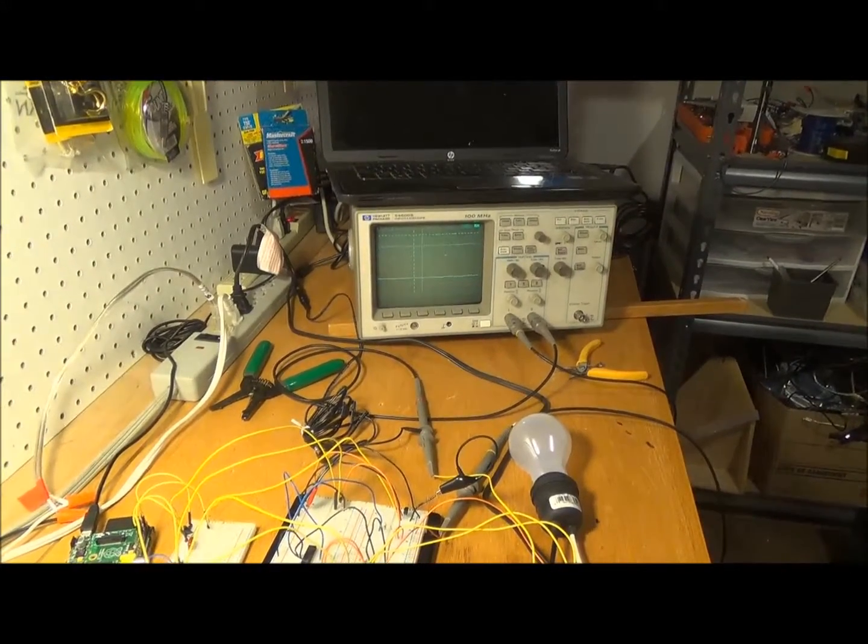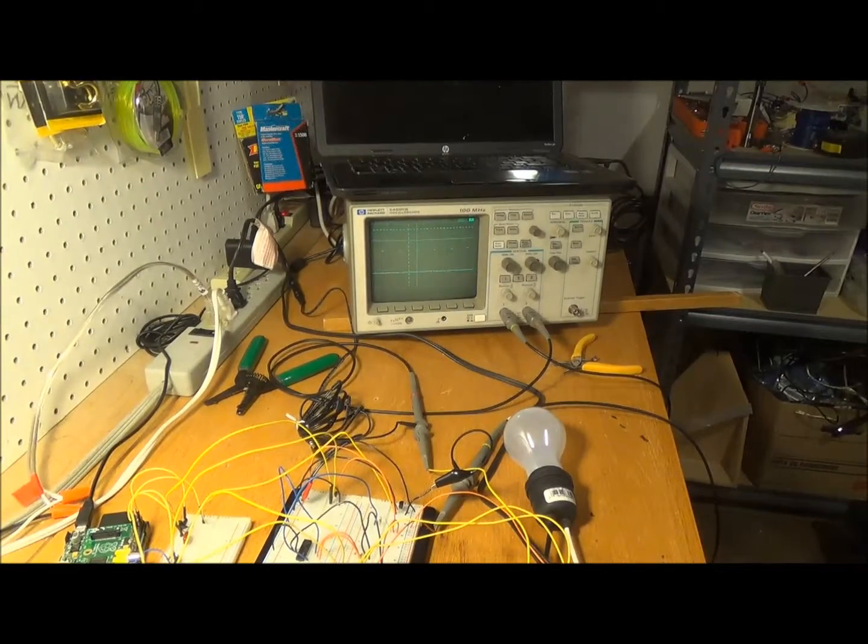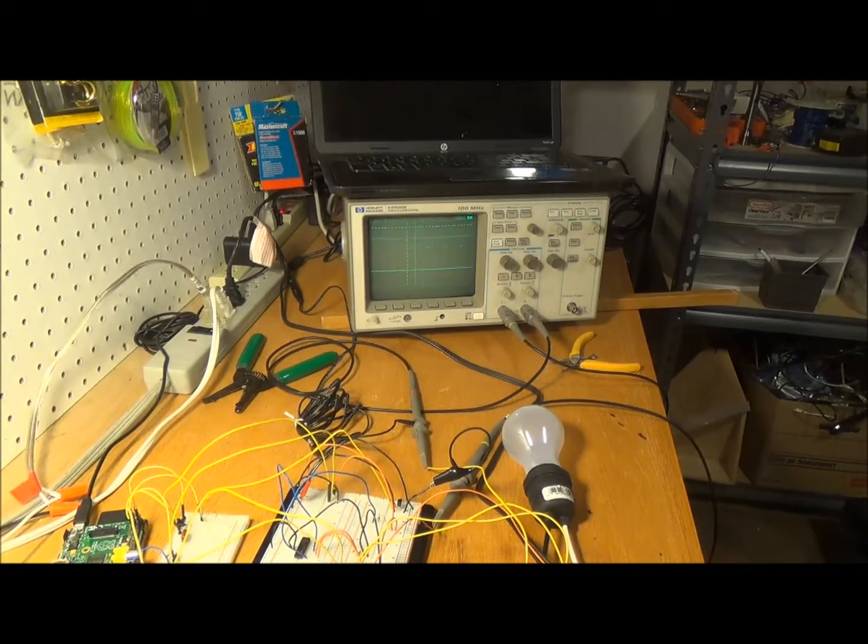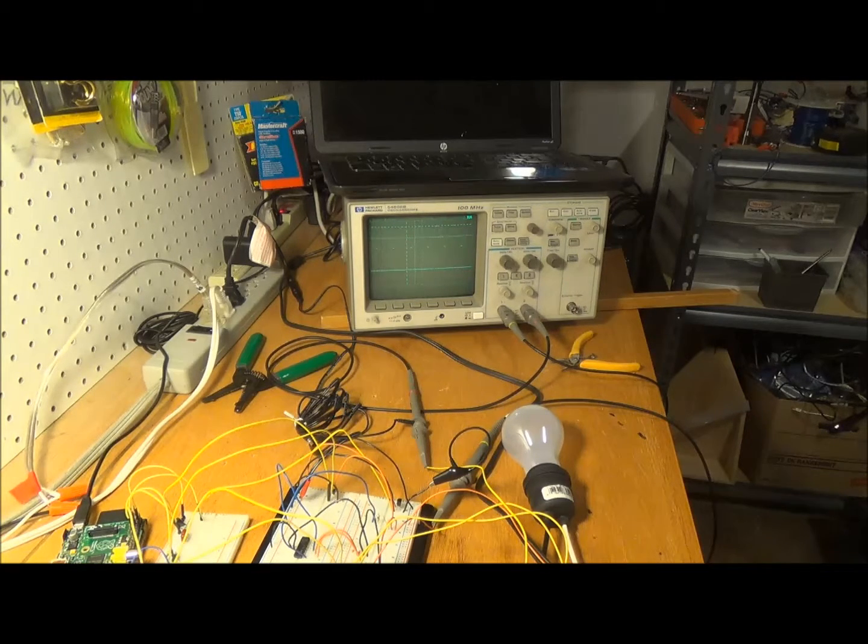I have my oscilloscope over there, and the laptop running a Python script to do the controls for this AC load. I have 2 versions of this Python script. One will introduce a delay of 3 milliseconds after detecting the zero voltage crossing, and we'll see how that affects the waveform and the brightness of the light bulb. And then I will introduce a 6 millisecond delay, and then we'll see how that affects the waveforms and the brightness of the light. Actually, I'm in reverse order. We'll do the 6 milliseconds first.